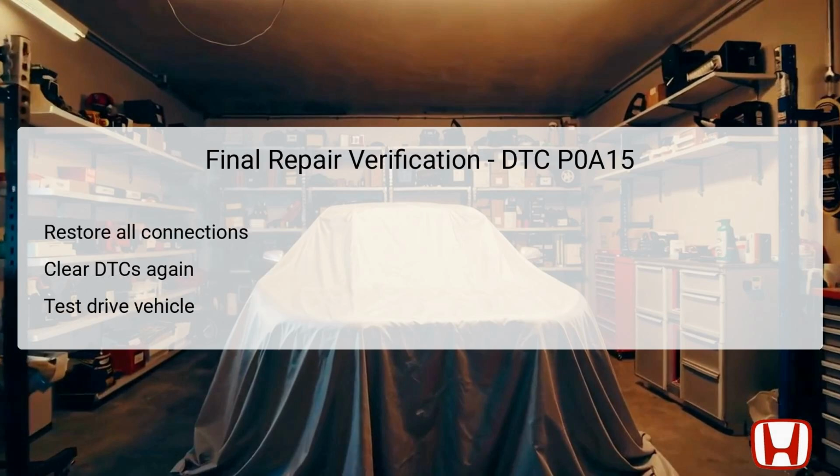After resolving the issues leading to DTC P0A15, it's essential to restore all connections secured during the troubleshooting process. Once everything is reconnected, use the HDS to clear any remaining DTCs from the memory, proactively preventing them from reappearing during future diagnostics. A test drive of the vehicle follows, which serves as a practical assessment of the repairs made.